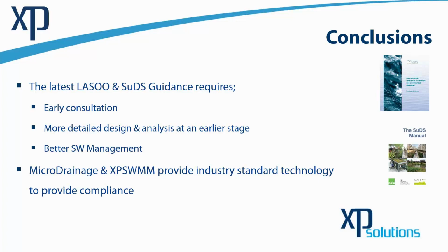I have another good one. Amir is asking how we decide what would be the extent of rainfall. For example, rain would be falling on how much area. I just decided on how much information I had, how much DTM I had available, but you can make it as big or as small as you think is required. Yeah, what I'd probably do there is go for the watershed extent. So we need to step right back and then identify where that ridge line is, where the watershed is, and then I'd probably apply the grid around the watershed, and then you can deluge the whole watershed.